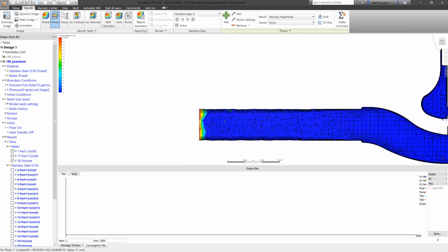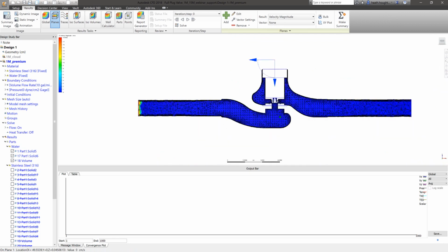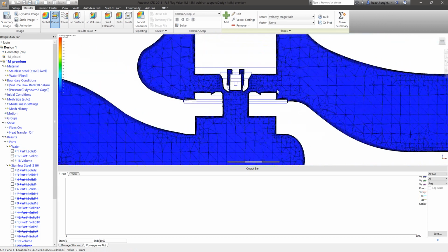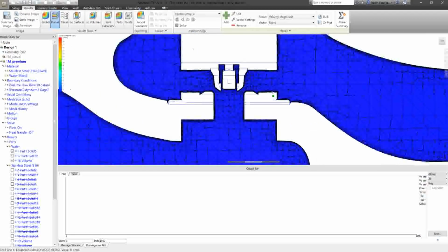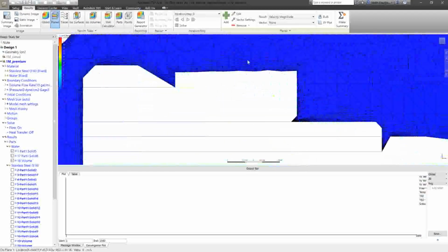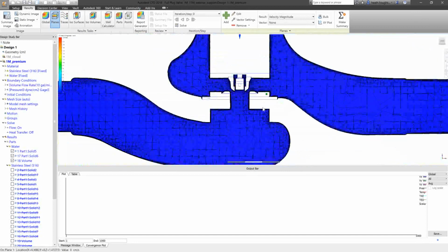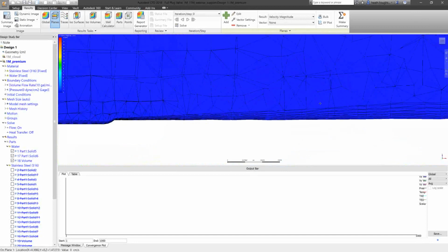So the distribution is still going to be similar. I threw a coarse mesh on here just so it would get through that meshing process quickly, and so we could really quickly see. The mesh looks different as far as now they're tetrahedral, so instead of being prisms, you see triangles in this cross section. But the distribution is going to be identical.